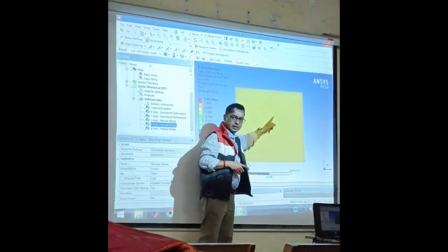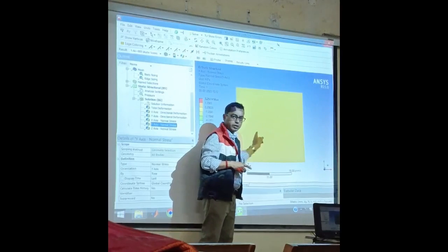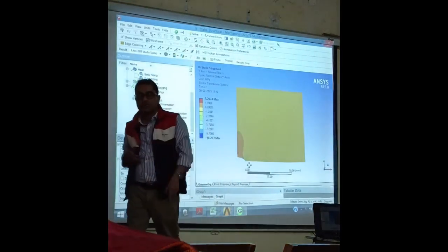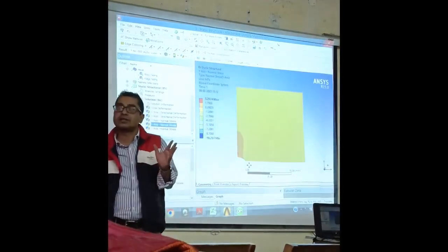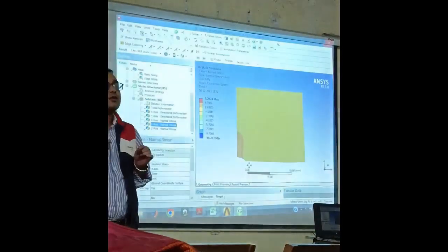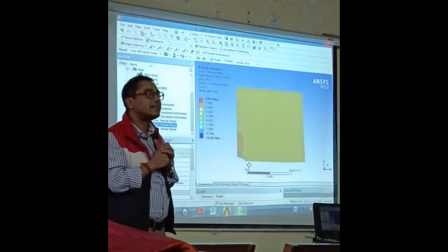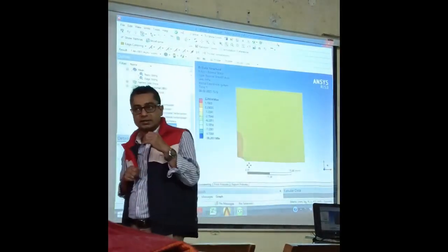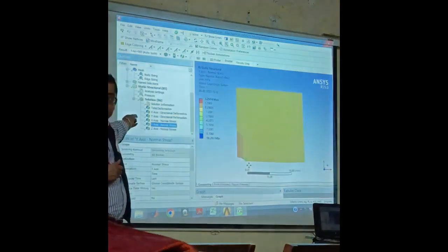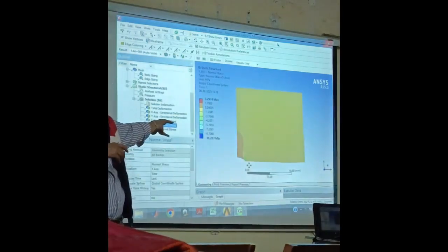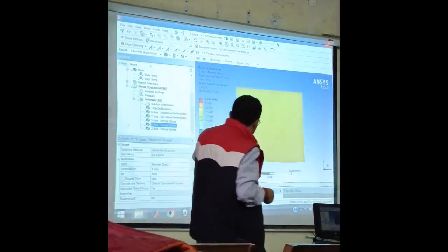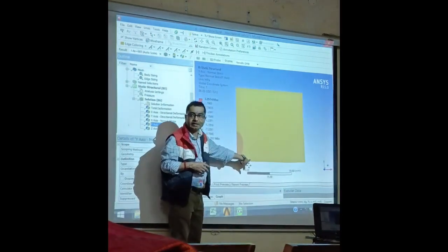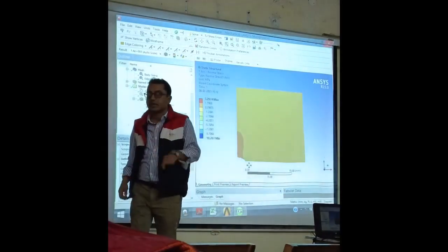I think you have seen this. This door is this shape or window is this shape. If you make it this way, then the stress concentration is supposed to be 4 times more. That is the way they have utilized the concept of superposition of the stresses due to the biaxial load. One is axial load and the other is hoop stress. So we are doing that mini part of this real problem. Now once I have changed this, the load path variation is less, that's why stress concentration is 2 here.